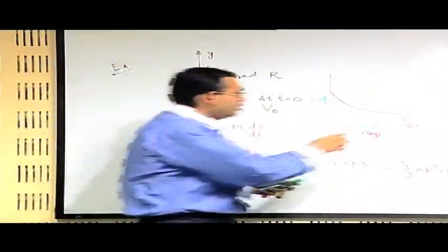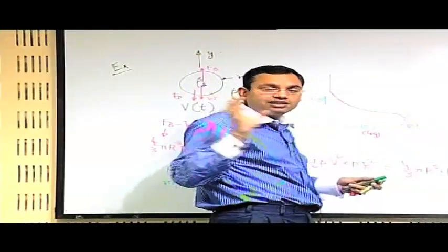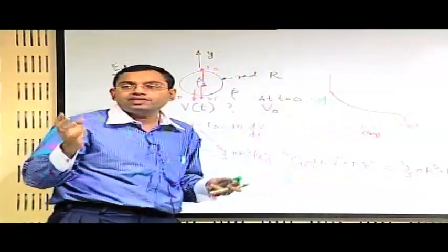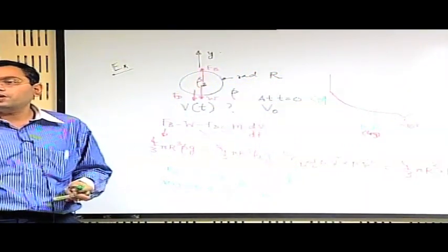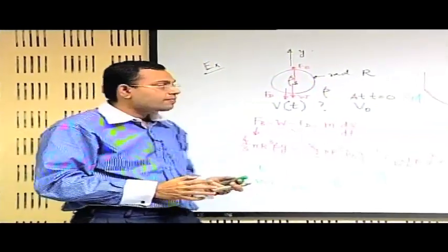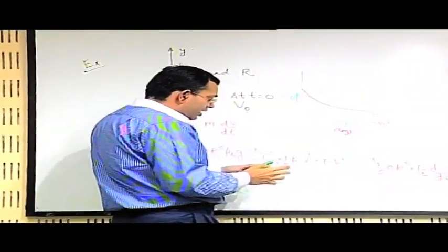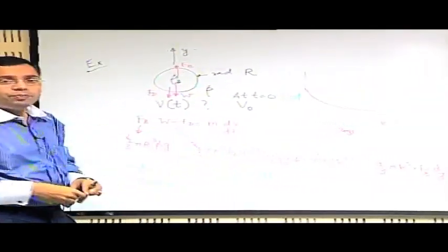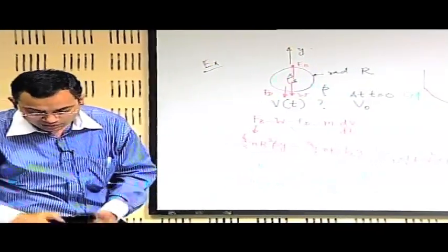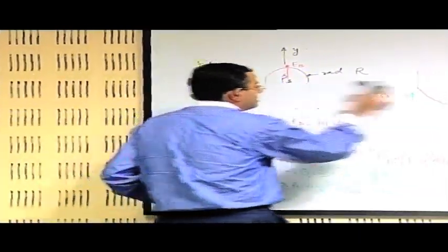So, this is all related to boundary layer separation. What we are trying to understand is that, towards high Reynolds number for flow past bodies with curvature, boundary layer separation is a very important phenomenon that dictates the total drag force. A similar behavior is there for flow past cylinders, and let us try to understand what happens for flow past circular cylinders as a special example.